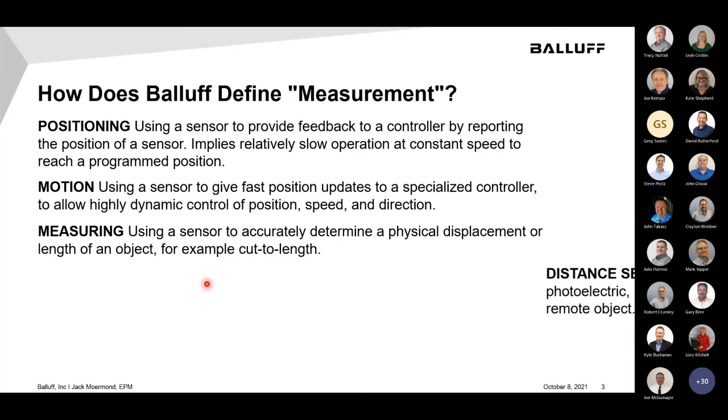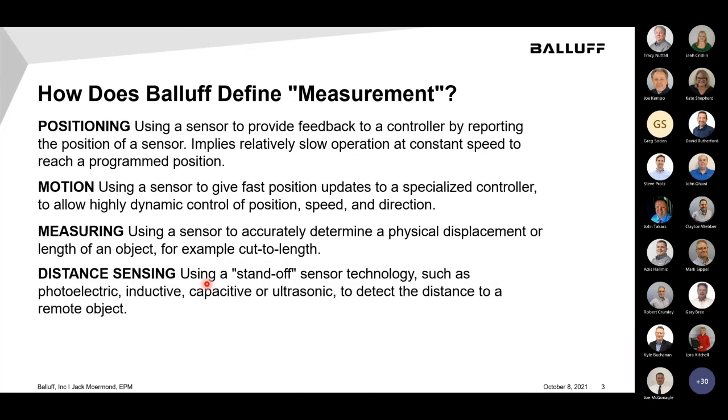And then the other one of key importance is distance sensing. So with distance sensing, we're using what we call a standoff sensor technology, if you will. So basically, this is going to be something like a photoelectric. The sensor is mounted off the moving device, and we're shooting a light beam at that target to determine what that distance is. So we're not positioning anything, but we're looking at that distance. So again, you're going to run into products like photoelectrics, inductives, capacitive, ultrasonic to determine that distance.